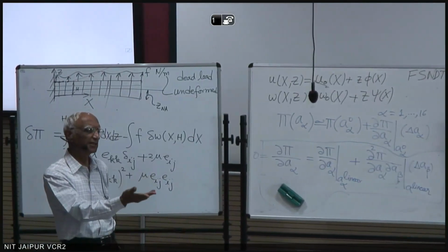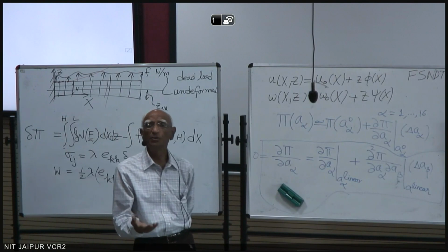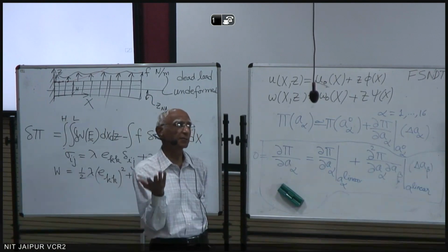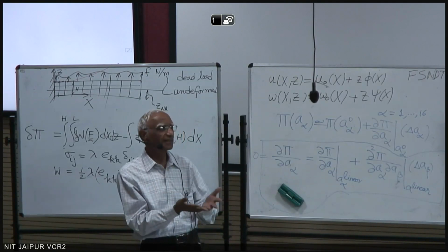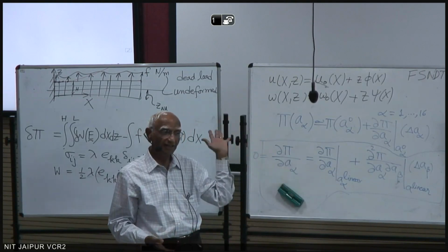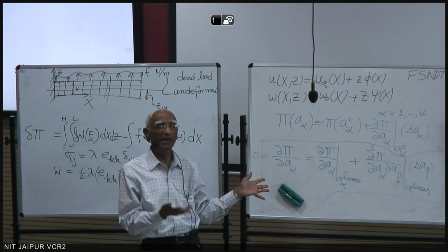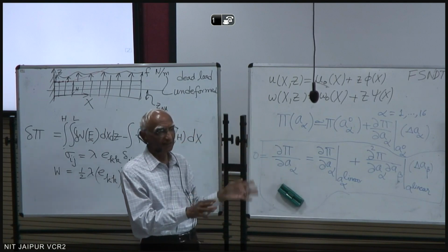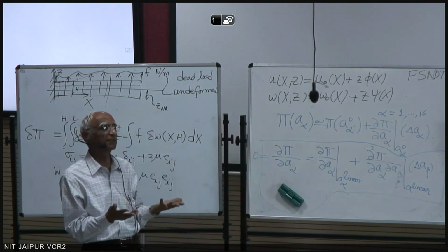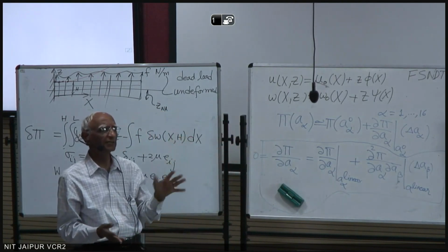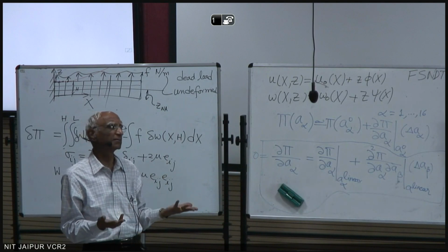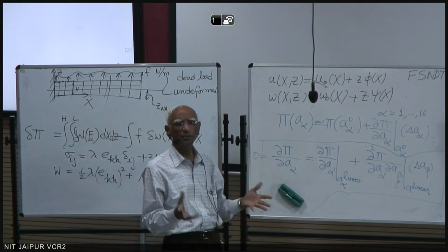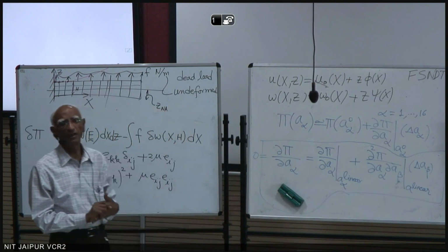If we had taken initial temperature instead of 50, say, 10, then the number of iterations would have gone up, because eventually we have to reach the values that we got. Going from 10 to 100, well, 100 was a given condition, so that was no problem. But at the intermediate points, you are at like 95. Going from 10 to 95 would have taken more time. So same thing here. If the initial guess is poor, we will have to do more work.